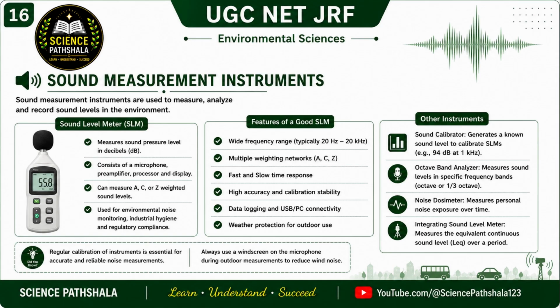Now let us discuss some important features of a good sound level meter. A good sound level meter should have a wide frequency range, usually from 20 Hz to 20 kHz. It should support multiple weighting networks such as A, C and Z weighting. It should also provide fast and slow response modes depending on the type of sound being measured. Other important features include high accuracy, calibration stability, data logging and USB or computer connectivity. For outdoor measurements, weather protection and a windscreen on the microphone are also important.